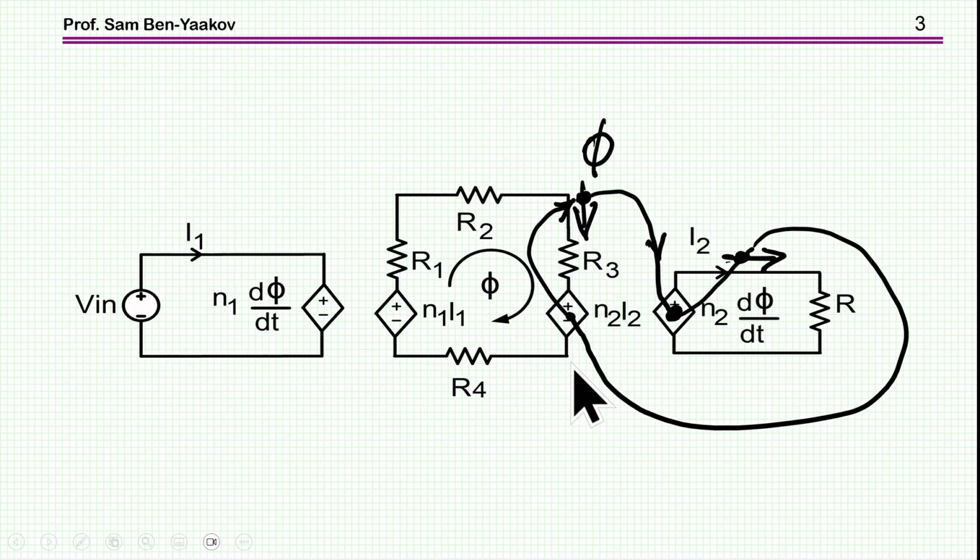It is important to realize that at the output section, that is at the output winding and the load, we have here actually a closed feedback loop, because we have here the flux. The flux is affecting this Faraday's law voltage generated, which is causing a voltage here at the output, and then this causes the current to flow due to the resistor, and now this current is coming back here as the voltage of this MMF, and this of course affects the flux. So we have here a closed feedback loop, that first of all complicates the analysis, and secondly it might cause some problems in simulation due to the racing between the signals. So this is one of the problems that one might have with this basic reluctance equivalent circuit.